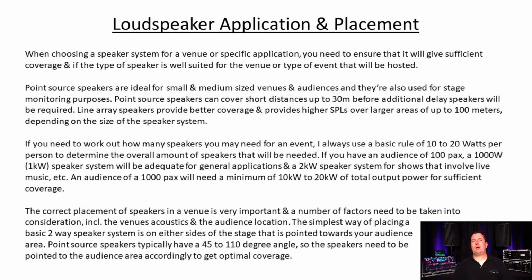If you need to work out how many speakers you may need for an event, I always use the basic rule of 10 to 20 watts per person to determine the overall amount of speakers that will be needed. If you have an audience of 100 people, a 1000 watt or 1 kilowatt speaker system will be adequate for general applications, and a 2 kilowatt speaker system for shows that involve live music. An audience of 1000 people will need a minimum of 10 to 20 kilowatts of total output power for sufficient